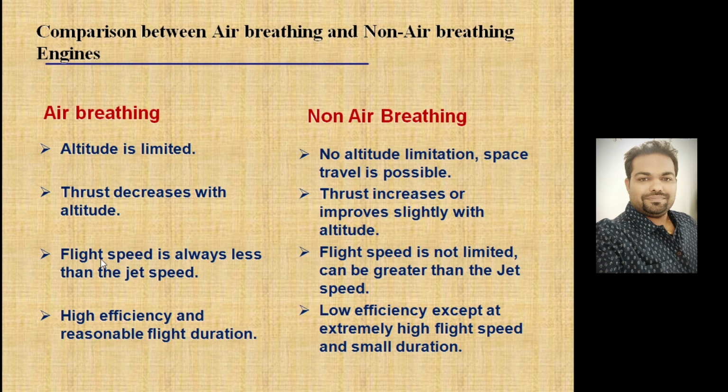And third point, flight speed is always less than the jet speed in air breathing engines. The speed at which the hot gases are expelled through the nozzle is high, but the reaction we get out of it will be lesser. So the speed of the vehicle is lesser than the jet speed. But in the case of rocket engines, flight speed is not limited, and can be greater than the jet speed.